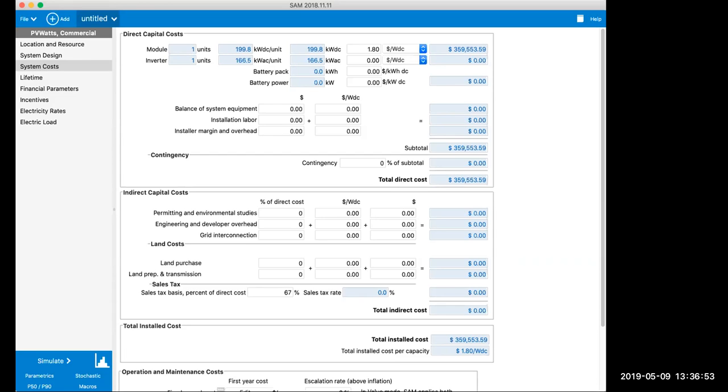Now, interestingly, my installer friend said that you have this disconnect, right? That's there for theoretically people to use, right? But a general lineman is not actually legal to use it. A first responder, I suppose, might be able to, but a lineman, they are not supposed to touch anything on the customer side of the meter unless they're a licensed electrician, with certain rights. And so, if they just come out and they're a lineman, they're not supposed to flip that.